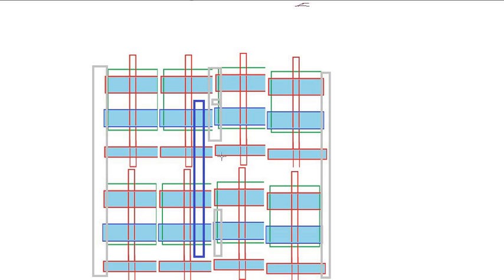It says that you have to draw a cut layer. The moment you draw the cut layer, the highlight goes away and it will be treated as a separate connection on this side and a separate connection on this side. So you draw a cut layer, you draw a vertical metal one on top of it, and you have the option of maneuvering the signal, making a vertical connection from top to bottom over here. Likewise, if I have to make a connection from here to here, I will draw this and make a connection here. I mean, yes, you have to use different metals. I'm just showing it for the sake of it, right?